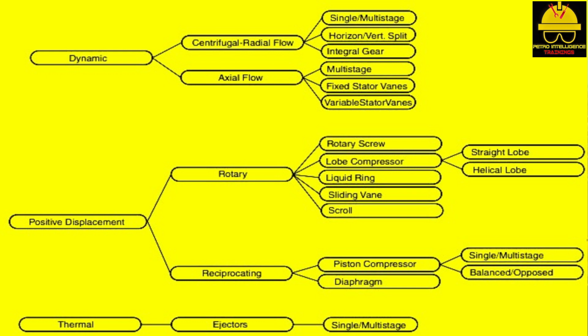A compressor is part of a much larger system. The system's resistance to flow typically dictates compressor performance. Minor problems are occasionally experienced with compressor systems. These troubles are usually the result of dirt, adjustment problems, liquid in the system, or inexperience in operating the system. Experienced technicians can quickly fix the problem by making the proper adjustment, cleaning the equipment, replacing a minor part, or removing an adverse condition.